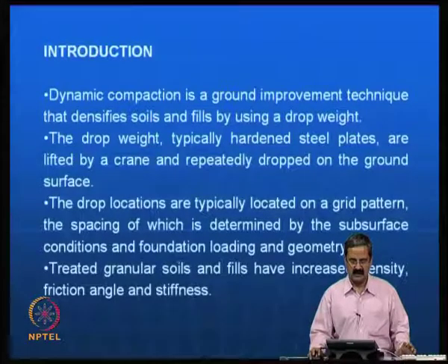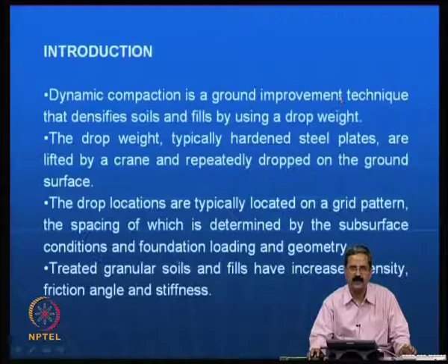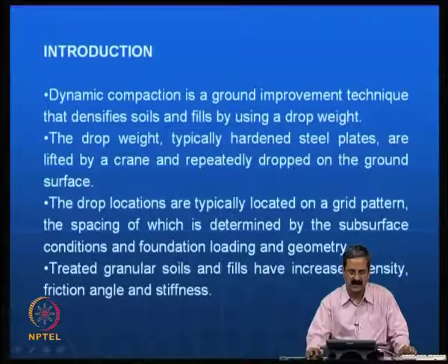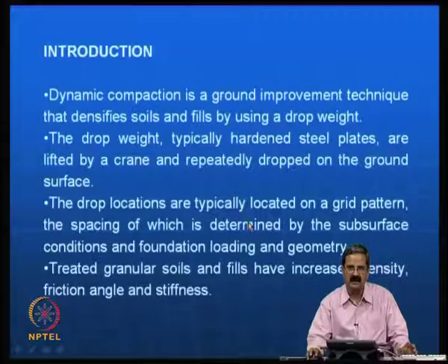So, as I said, dynamic compaction is a ground improvement technique which can be very useful, which densifies fills by using a drop weight. And as you saw just now, the drop weight can be a hardened steel plate, or a circular weight. It is lifted by a crane and repeatedly dropped on the ground surface.